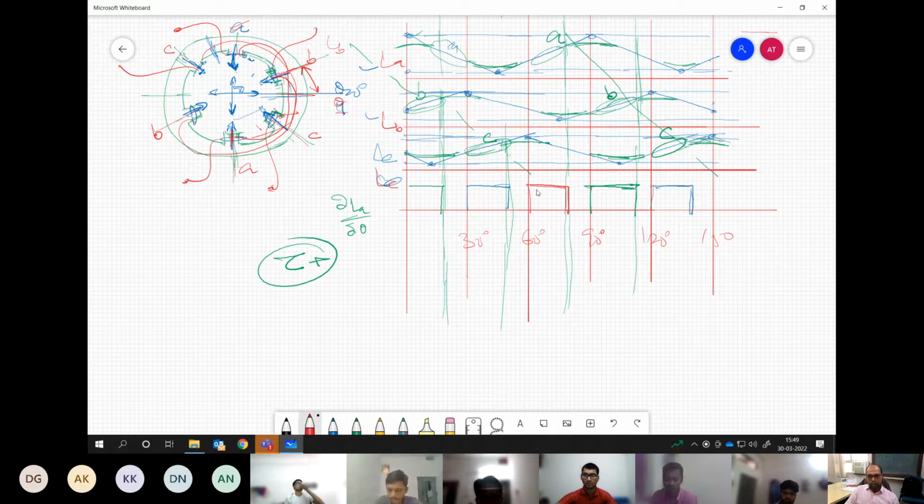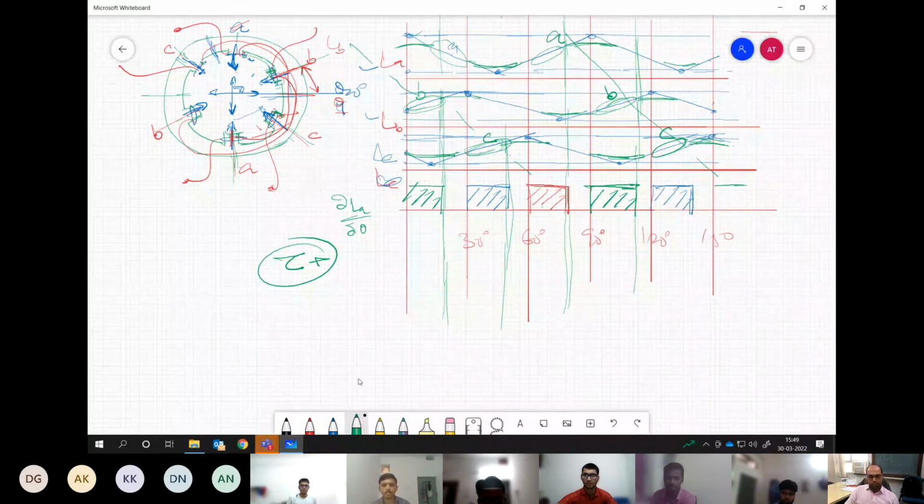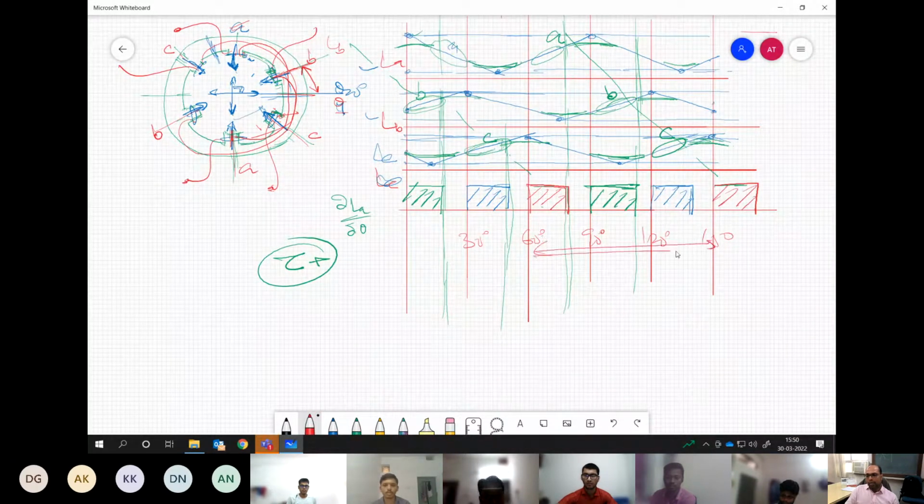So these boxes which I am coloring, this is the duration for which this particular phase is excited. And then you have torque generated corresponding to that phase. So A current is applied only during this zone, and then it will be applied next over here. So there is a clear gap of 90 degrees. That's the meaning, right? The rotor is having 90 degree angle. So anything will repeat only after 90 degrees for any phase if we are talking about. Am I clear? Correct?